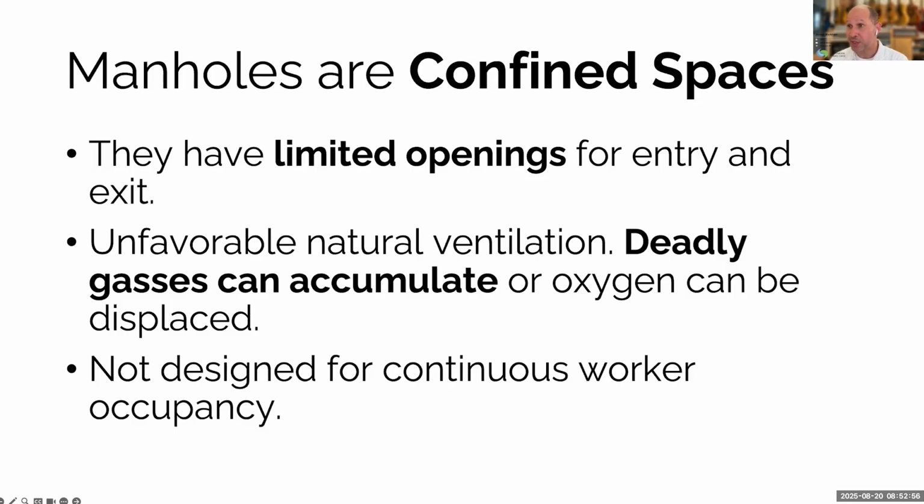CO2, sometimes oxygen. It's not that the gases are deadly, it's just that the oxygen's been displaced. And there have been multiple occasions of somebody going into a manhole without doing a sniffer test, without the appropriate gear, collapsing, and then somebody going in after them to try and help them and them collapsing too. So we'll discuss that more in a later section, but just remember manholes are confined spaces.